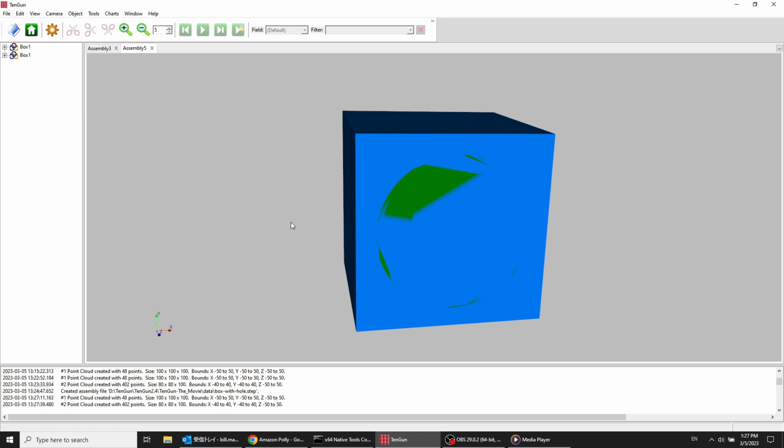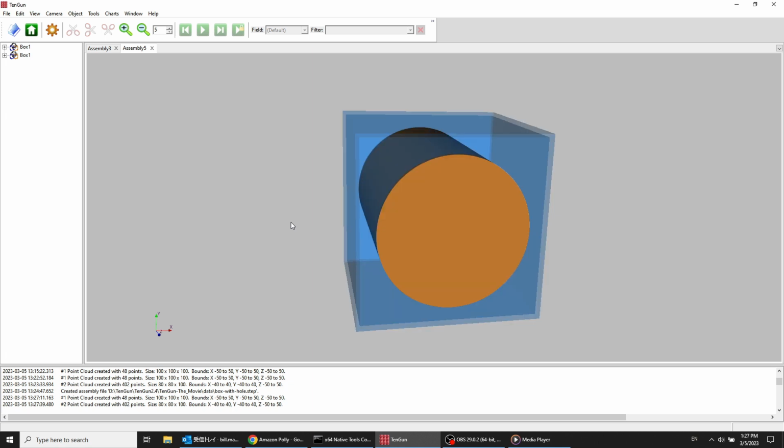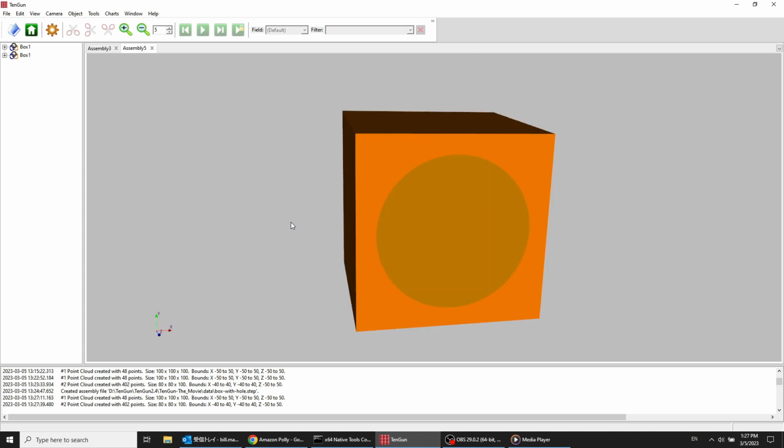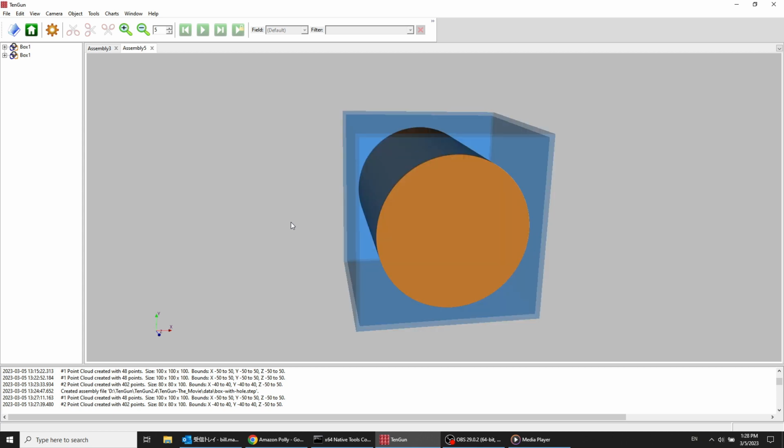So I need to do two things. First, press the N key to cycle through the objects until the pipe is the active object. You can also select an object by right-clicking on it, but the pipe is obscured here, so I'll use the keyboard instead.